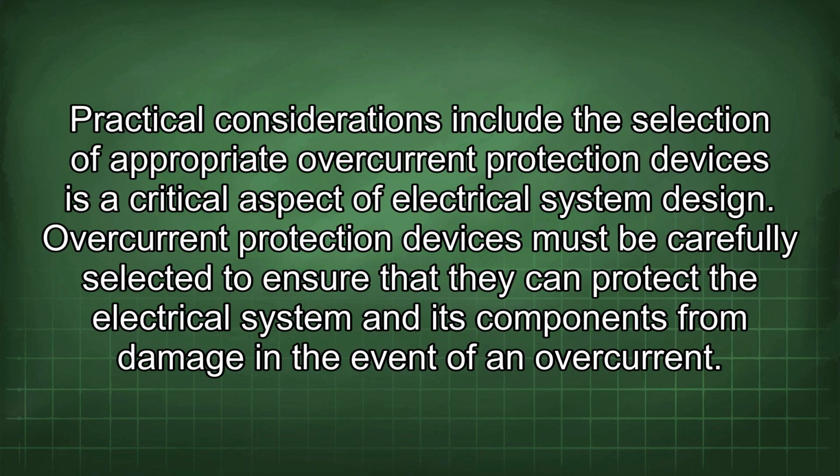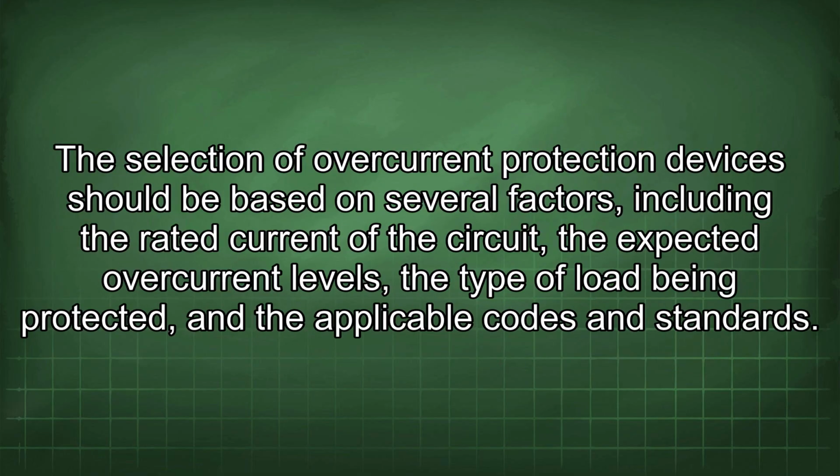Practical considerations include the selection of appropriate overcurrent protection devices, which is a critical aspect of electrical system design. Overcurrent protection devices must be carefully selected to ensure that they can protect the electrical system and its components from damage in the event of an overcurrent. The selection should be based on several factors, including the rated current of the circuit, the expected overcurrent levels, the type of load being protected, and the applicable codes and standards.